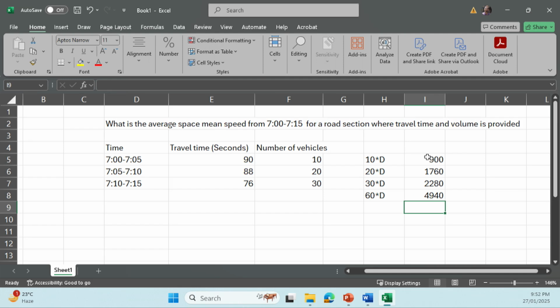But I want you to think beyond harmonic mean. Look, average speed is the total distance traveled over total time taken, and you calculate that average speed accordingly. So maybe you can attempt this: travel time is given instead of speed, so you figure out average travel time. Because the numbers of vehicles are different, you take the weighted mean of average travel time and invert it, and you will get the speed.